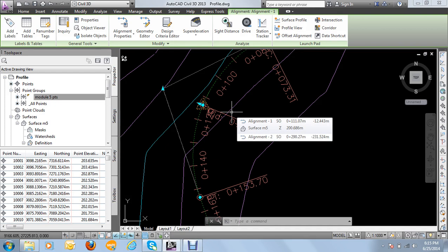Another, you can also check more when you create the profile, because you have a lot of standards that you should incorporate, like maybe K values for the road, minimum stopping sight distance, and all those. So after you create the profile, that is the final. It's where almost all the design checks have been checked. So from there, you just create other things without putting much consideration on those design standards.